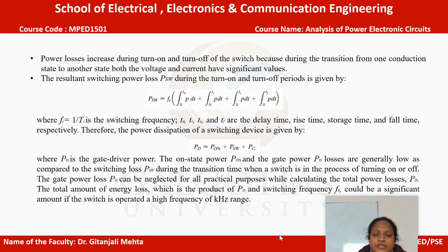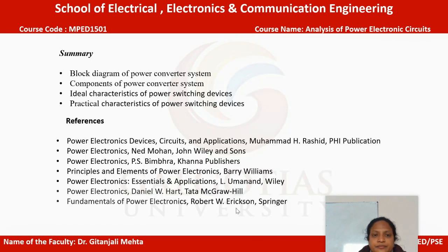The total amount of energy loss, which is the product of Pd and switching frequency Fs, could be a significant amount if the switch is operated at the high frequency of kilohertz range.